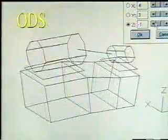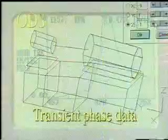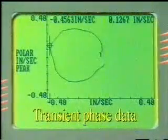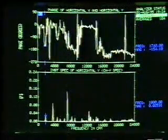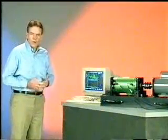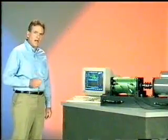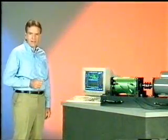The phase data can be entered into an ODS program to animate the motion at operating speeds. Transient phase data provides the necessary information about resonance frequencies and can be displayed as Bode plots or a Nyquist plot. Multi-channel phase can provide the phase relationship at every frequency of the spectrum. While many areas have been covered, we've only highlighted the most common phase characteristics and measurement practices. We realize that unique designs and applications necessitate special considerations for phase measurements and analysis.